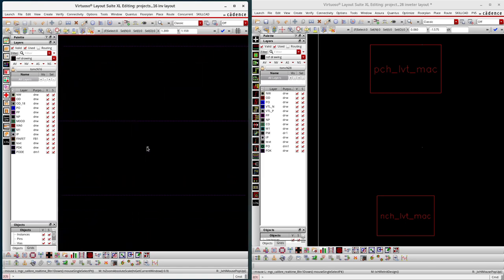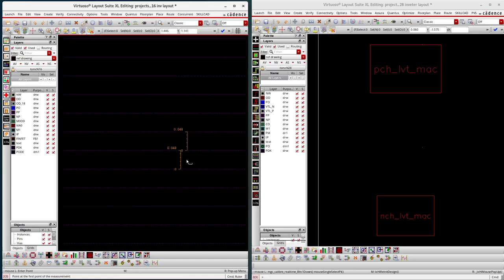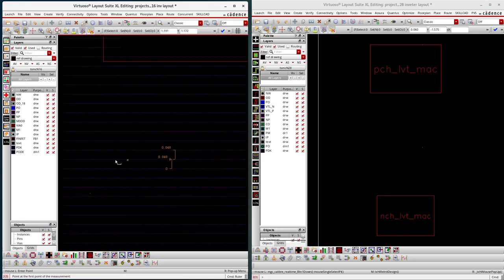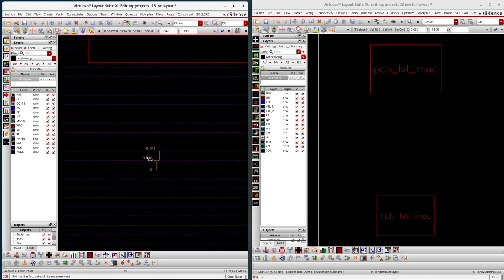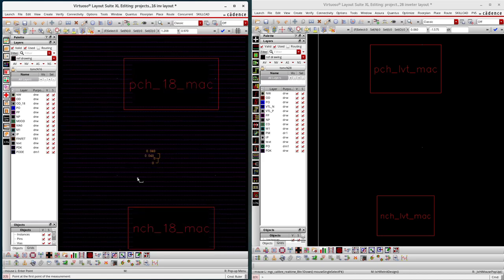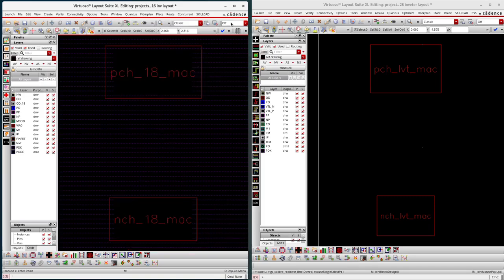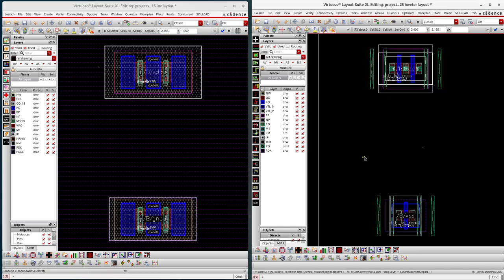You can see some straight lines here. These straight lines are available only in the FinFET technology node. These are the fin boundary layers in the FinFET design. The fin boundaries will be continuous across the entire layout. Even if you are not placing your device, that doesn't matter. Wherever there are empty spaces, the fin boundary will be continuous. So let me enable these devices one by one.